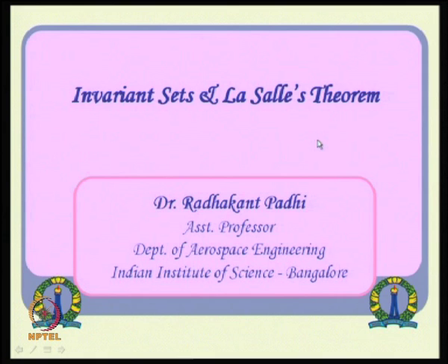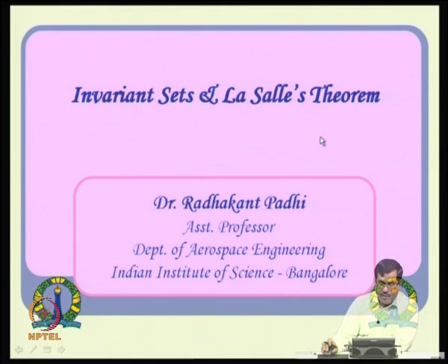Now, how about the other issue. What happens when, for this Lyapunov function, we end up with V dot being negative semi-definite? What do we do about that? That is where we need the concept of LaSalle's theorems, before which we want to study what is an invariant set, limit set and things like that. So, let us see what that is here.